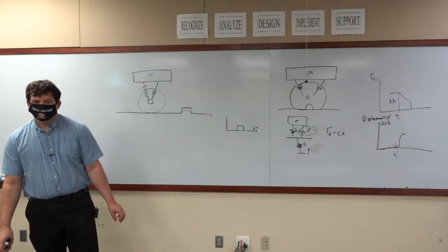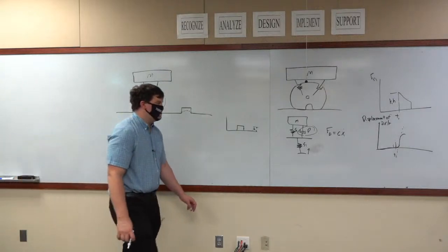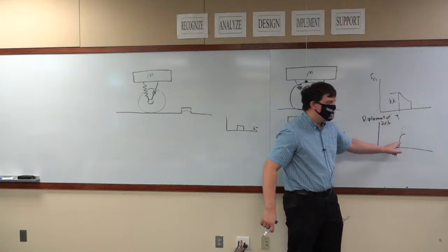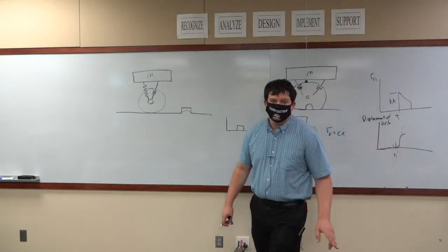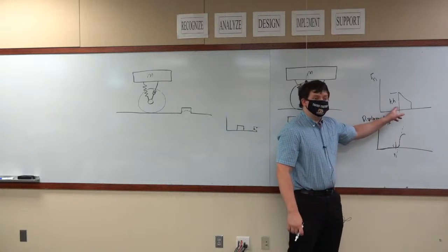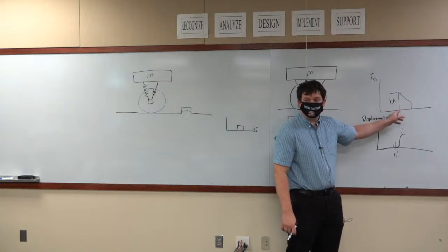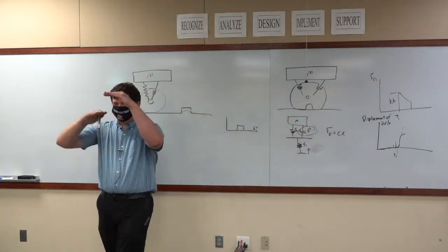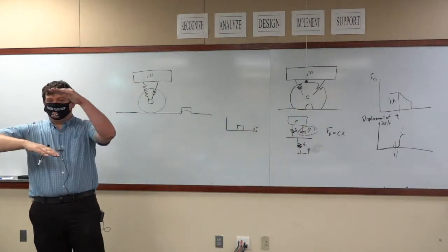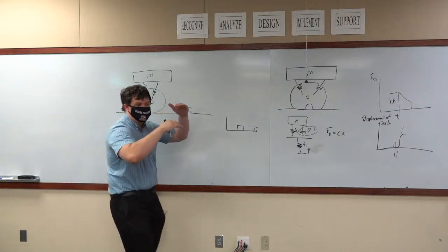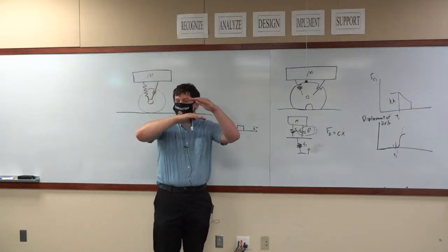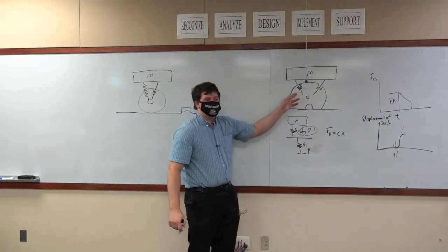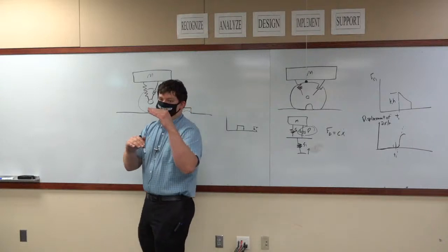Does that make sense? So your axle, yes, it does accelerate after the impact, but it does not immediately jump. For that reason, all of the force has to be taken here through the spring because the top of the spring isn't moving. Only the bottom part of the spring is moving. But as the bottom part of the spring moves upward, as your tire deforms and starts pushing up on this axle, your damper and your spring will also begin to compress.